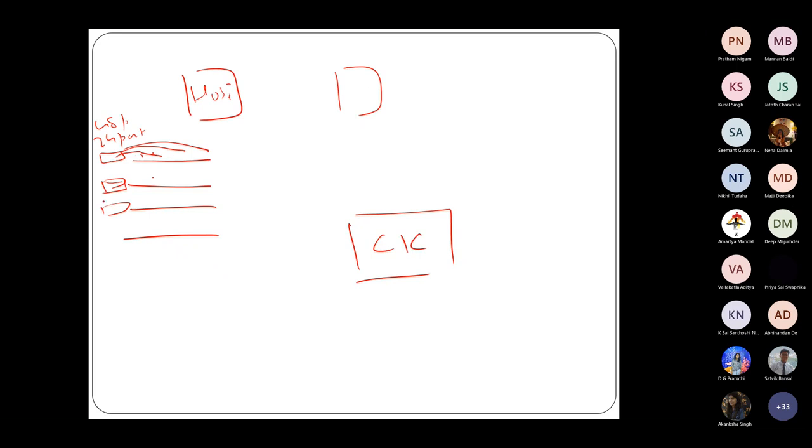Why do I need to put two? That is where the distance will come. You'll have to see from this switch what is the maximum distance of a room out here. That will depend on the geometry of the building. And remember, you cannot just put a hole in the roof and take the wire through there. So shortest distance, basically. You'll have to guide it around the walls and so on. So then you need to know what kind of things to choose. Cost is a big factor because there are too many wires out here. So you need to know the properties of the medium.